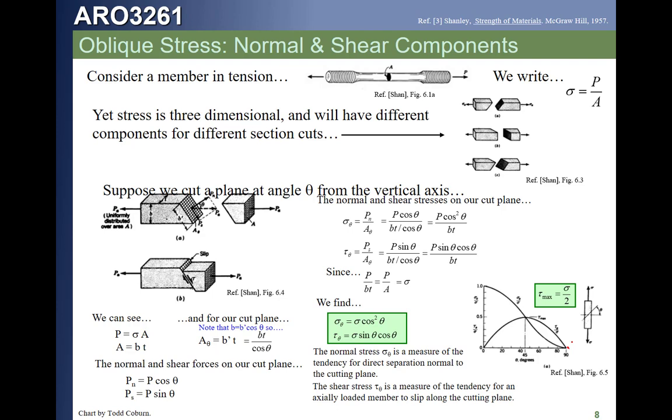However, shear stresses and normal stresses have a different magnitude, and so in order to show them on the same graph in a fashion that's easiest to understand, we're going to take whatever the stress is, and divide it by that original stress. So the stress on the inclined plane divided by that original stress that we calculated back here, P over A. And in the same way, we're going to take that shear stress on that inclined plane and divide it by sigma. That's what we're seeing here.